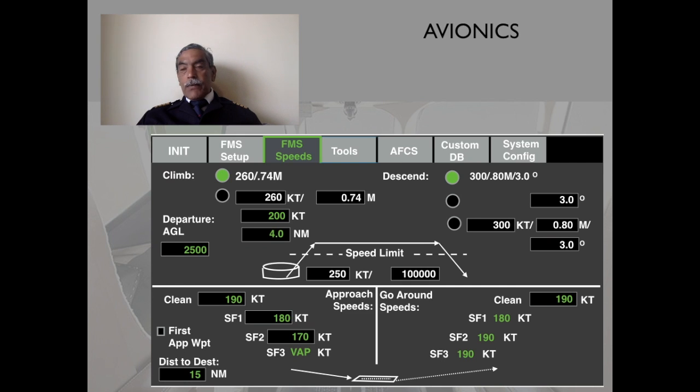So you can experience a change in speed of the aircraft if there is a disconnect of the localizer or glide slope. Lastly, the approach speed changeover point. That means you are descending at 250, and at some point it has to drop speed from 250 to 190.